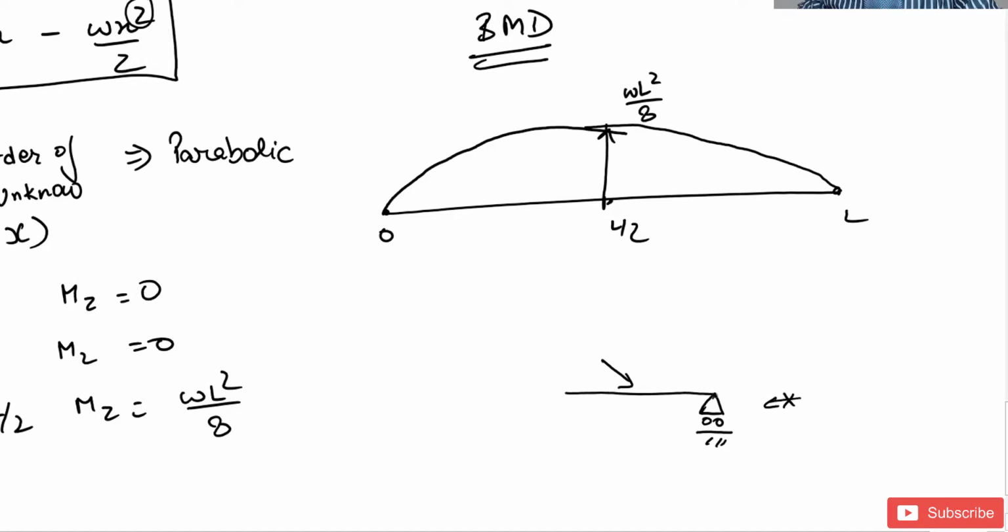However, when this point is trying to go down, this is offering some resistance. So it is offering some resistance in the Fy direction. However, it's not giving any support in either the Fx or the moment. So this point is easily turned. It can rotate around this point. So Mz is not available. Fx is not available. Only Fy resistance is available.